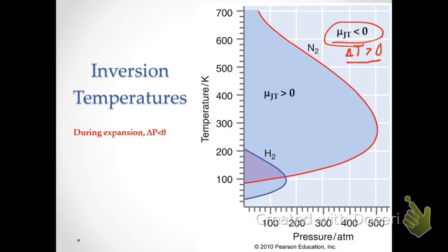That was because in that particular temperature and pressure regime, the Joule-Thomson coefficient for carbon dioxide was greater than 0, and when the CO2 gas expanded from the high pressure region inside the tank to the low pressure region outside the tank, its temperature dropped significantly. And that's going to occur when attractive interactions are very strong. The stronger attractive interactions are going to cause a temperature drop during a particular expansion process.